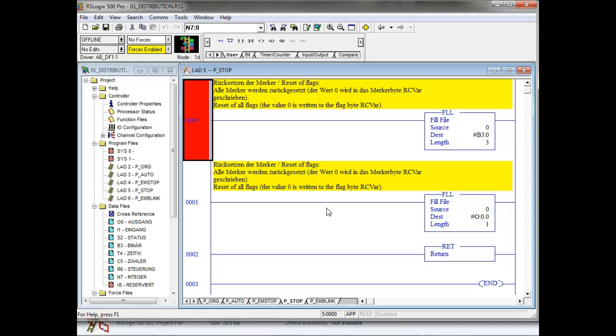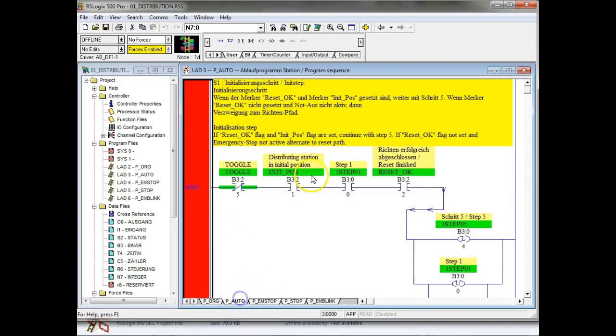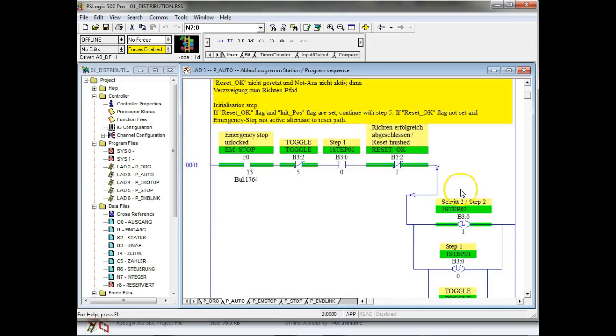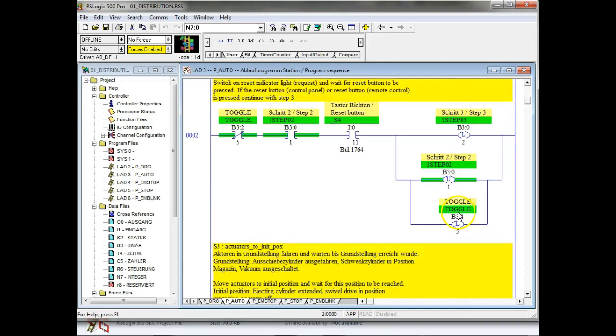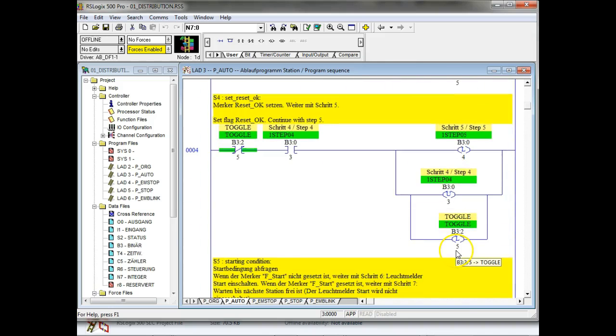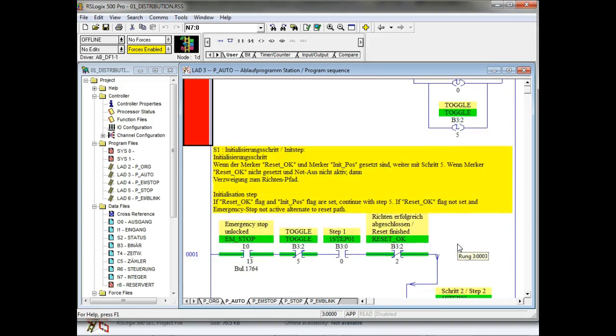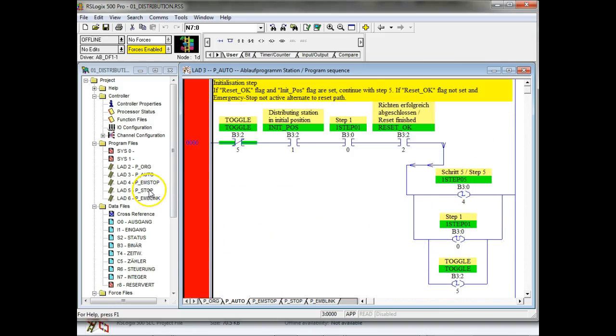It makes sense. And what it does is these bit files are used in the auto program right here to go out and set. So see, here's all the bit files right here. So instead of me going back here and unlatching all these things and trying to do a ladder program, what did they do? They just set them all to zeros with one whack. Okay.